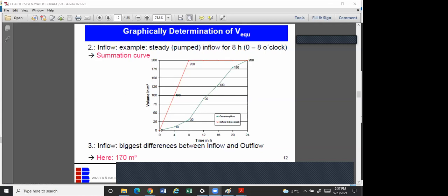Okay, but if you do water demand, which I'm going to show, I also tell people to do that as a guide. When you do your total water demand, convert it to daily factor. You can use it as an idea to say this is the maximum tank size I can use. In other words, if I'm going to pump once a day and store water for 24 hours, this is the maximum tank size. But that tank can be so massive that you need to break it and say, I'm pumping twice, once, thrice, or 4 times a day.